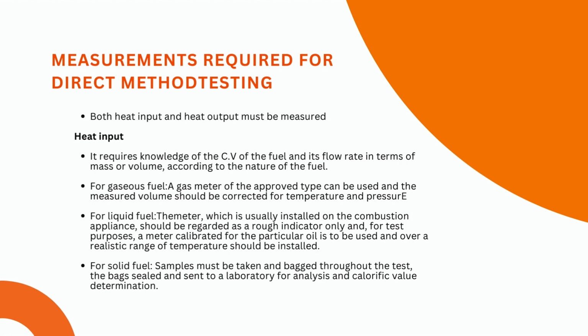For liquid fuel, heavy fuel oil is very viscous and this property varies sharply with temperature. The meter, which is usually installed on the combustion appliance, should be regarded as a rough indicator only, and for test purposes a meter calibrated for the particular oil is to be used and installed over a realistic range of temperature. Even better is the use of an accurately calibrated day tank.